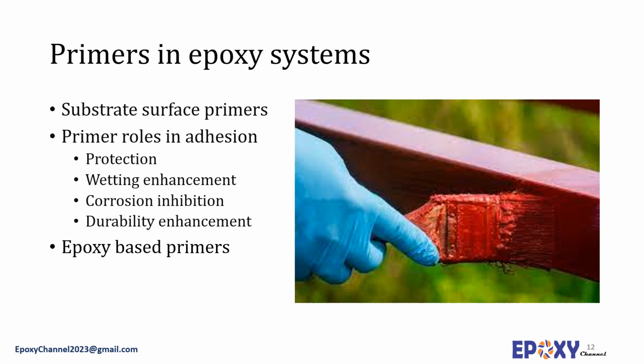Employing primers can also solve the potential wetting problems that might be associated with the use of certain adhesives. In addition, corrosion-inhibiting primers, which comprise an epoxy and a strontium chromate in a solvent base, are often suggested with aluminum alloys following anodizing pretreatments.